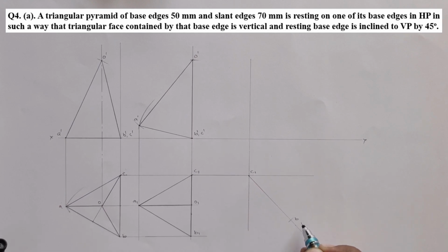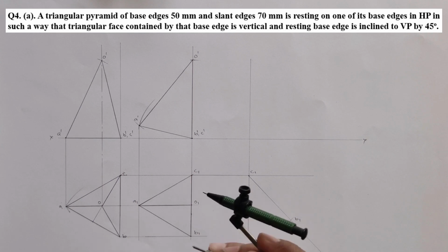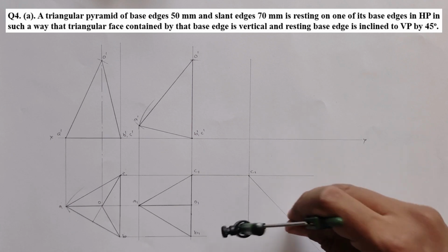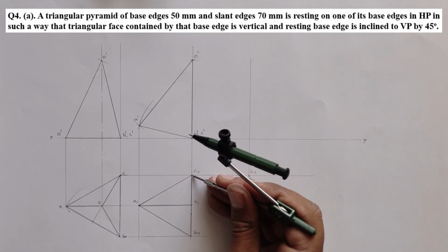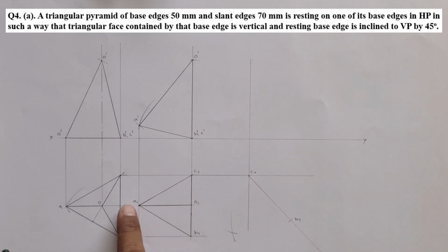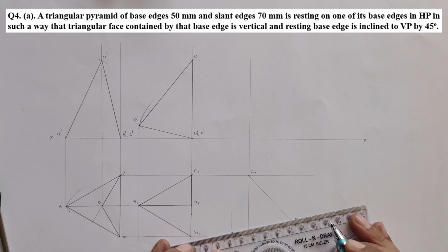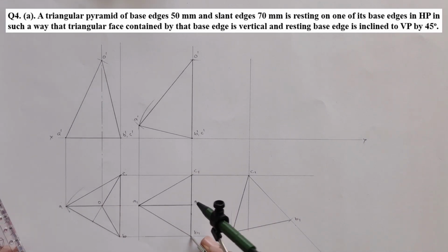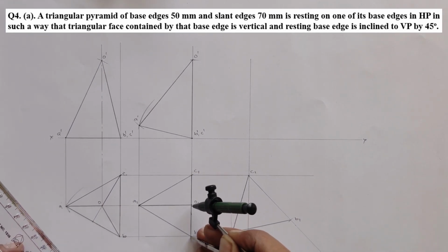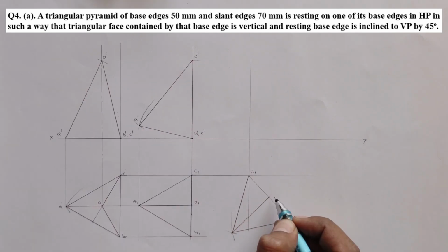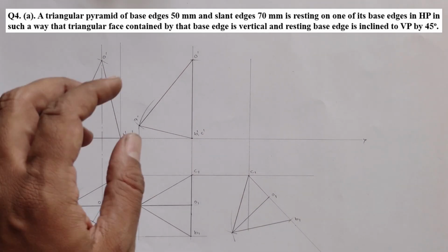Dimensions are not changing, so the names remain the same. Keep this distance here, drawing one arc, and this is again the same, cutting it. So the distances A to B and A to C will be the same. Let's use the arc method to locate the last point, O. So this is O1.